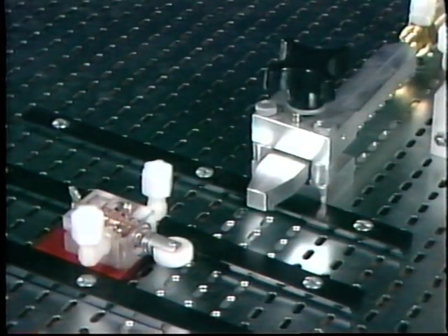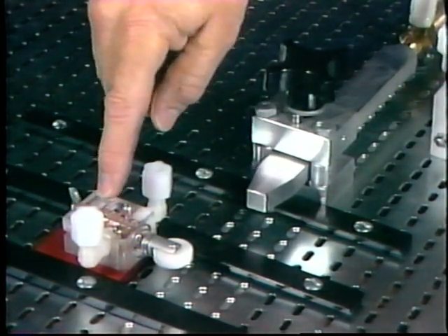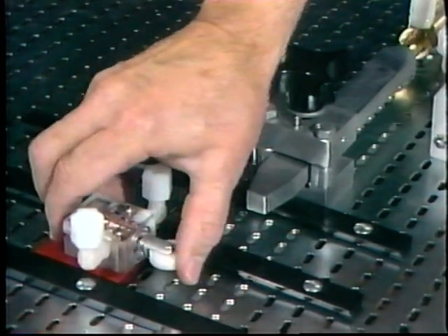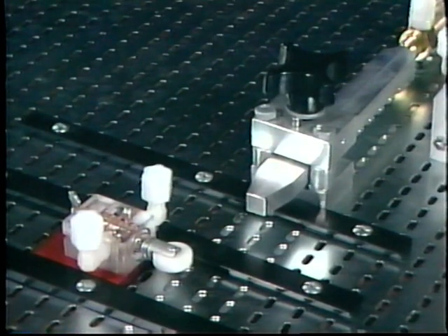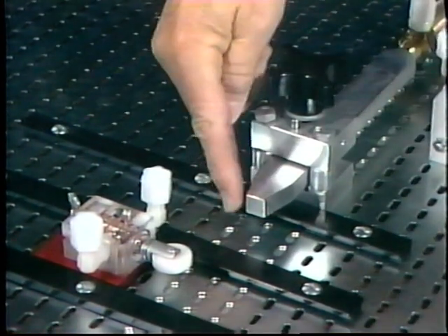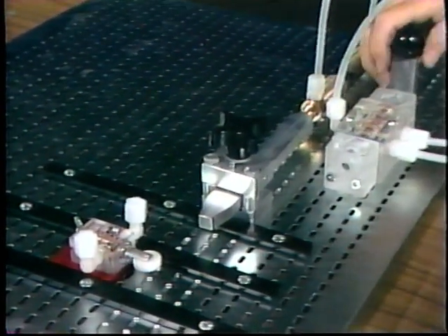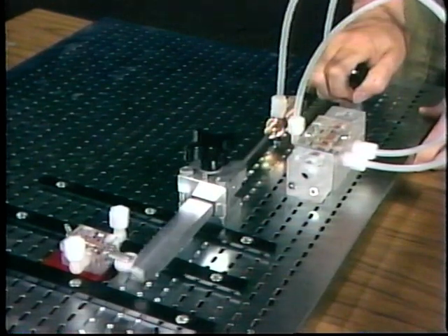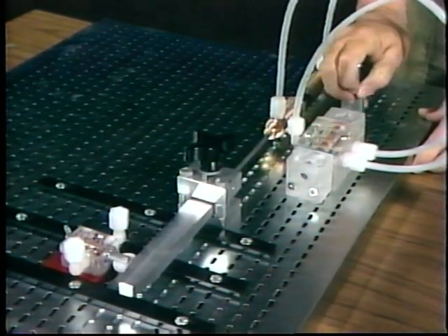Mechanical actuation is usually accomplished with a cam. A cam valve is simply a valve with a roller or ball mounted on the end of the spool extension. The roller is in contact with some part of a machine, frequently a cam which is mounted on a cylinder rod.